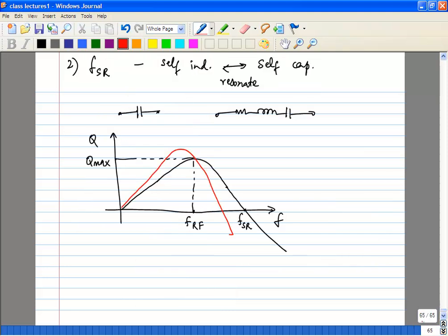So let's say we have an inductor. Now what we're going to do is put a ground shield. You will still have some eddy current flowing through the ground shield, but because of the low resistivity, I square R losses will be lower. So let's assume that is the case for now. Next we'll look at what happens if that is not the case. Now, let's say this was on M6.